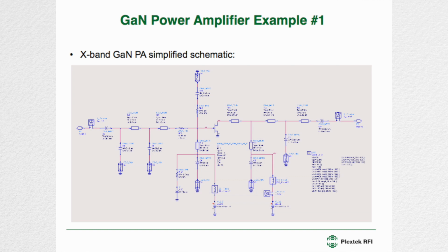You can see we've got a low pass structure on the output. We've got our drain bias here, a low pass structure on the input to take that low impedance up to our 50 ohm point over here. And this capacitance here presents a good short circuit in band. We apply VDD here. Similarly, at the input here, we apply a gate bias. This resistance and capacitance there is for ensuring lower frequency stability. It's not there to affect our in-band performance.